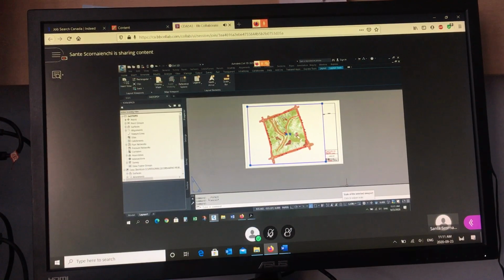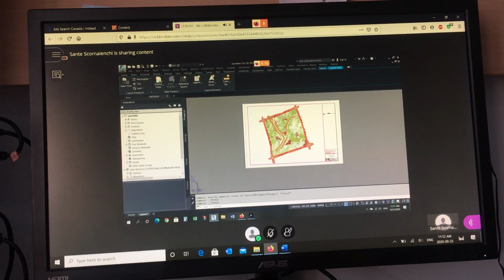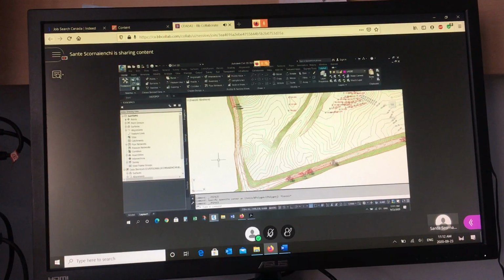Now, if you notice the icon here, this is paper space. If I click it here, I'll go into model space through paper space. And notice the icon, right? These are just X, Y axes. And if I double click out here, you'll see it looks like a triangle. And that's how you know whether you're in paper space or model space, especially if you're zoomed in.